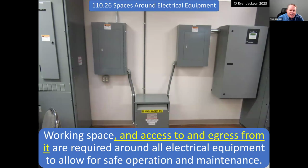And I understand it's a difficult one because, you know, equipment spaces, you got to have them, but they don't really make you any money in your building. You're not leasing it out and everything else. So I understand people don't want a huge electrical room. So what are the rules? I mean, how big does the electrical room have to be, or do you have to have an electrical room? Well, working space and access to and egress from that working space are required around all electrical equipment to allow for safe operation and maintenance.